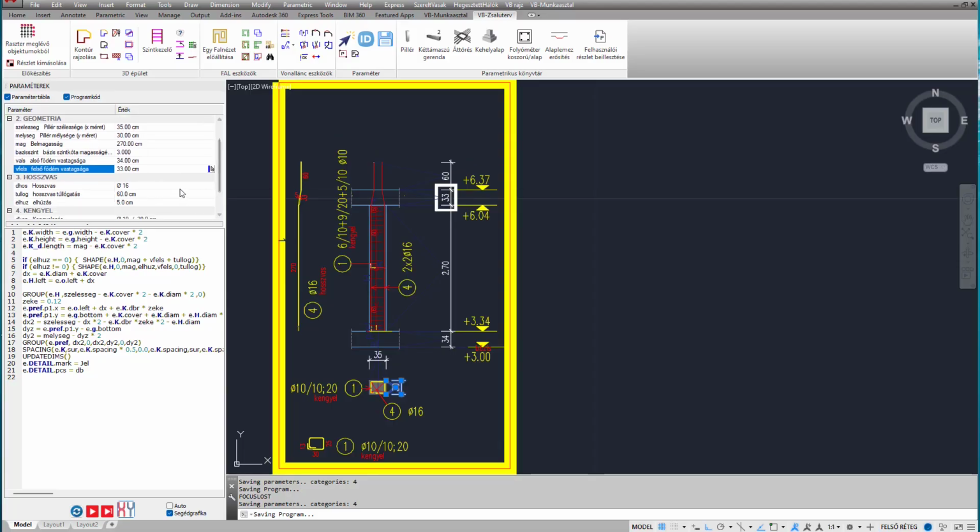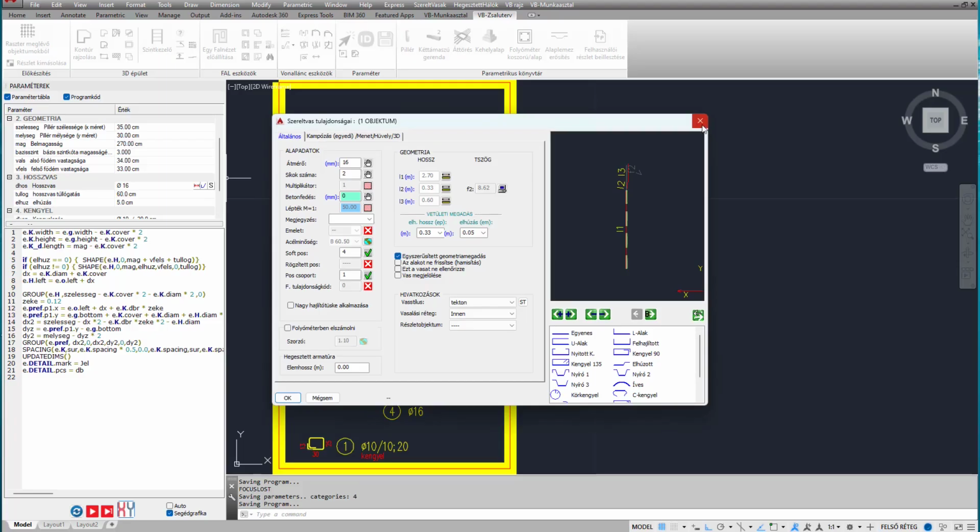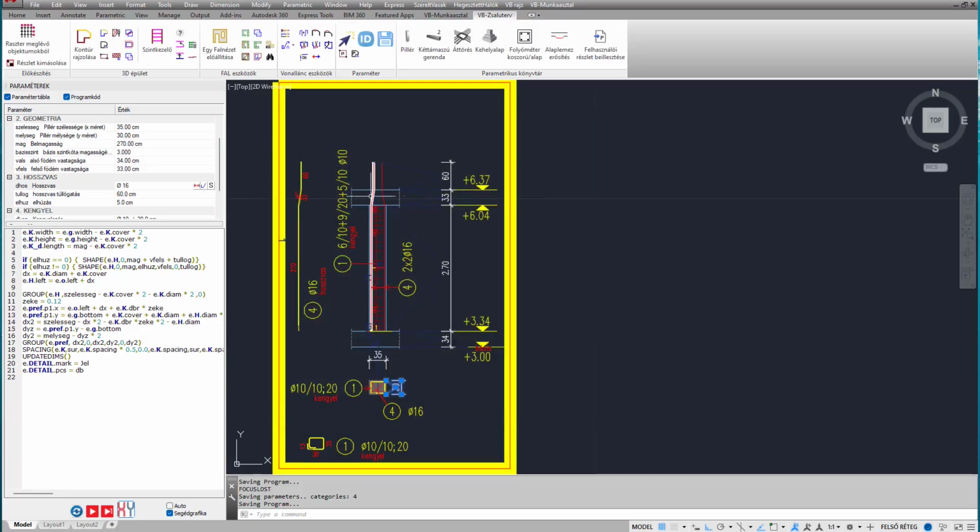The same applies to reinforcement parameters. If I click the longitudinal bar, it is immediately highlighted. For reinforcement parameters, there are 3 buttons to change values. One opens the reinforcement dialog, which contains the full longitudinal bar settings. Another allows a simplified diameter and spacing setting.